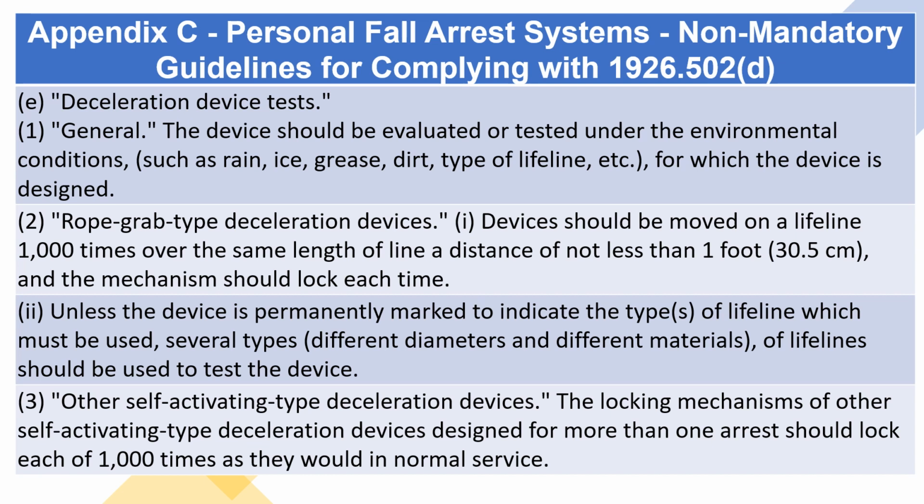3. Other self-activating type deceleration devices. The locking mechanisms of other self-activating type deceleration devices designed for more than one arrest should lock each of 1,000 times as they would in normal service.